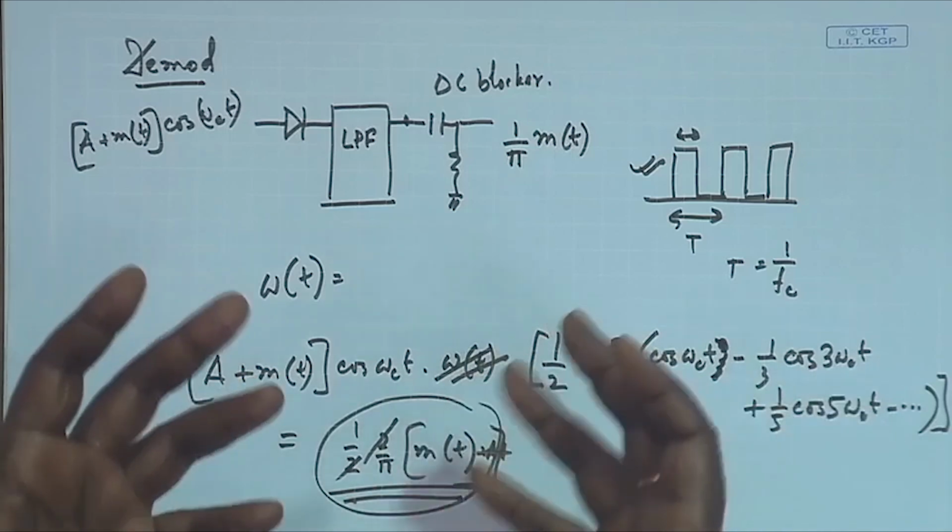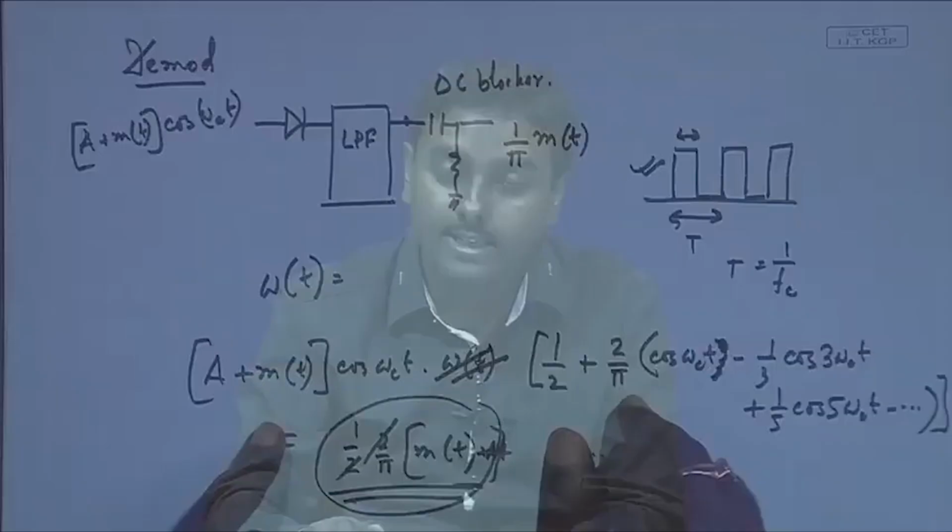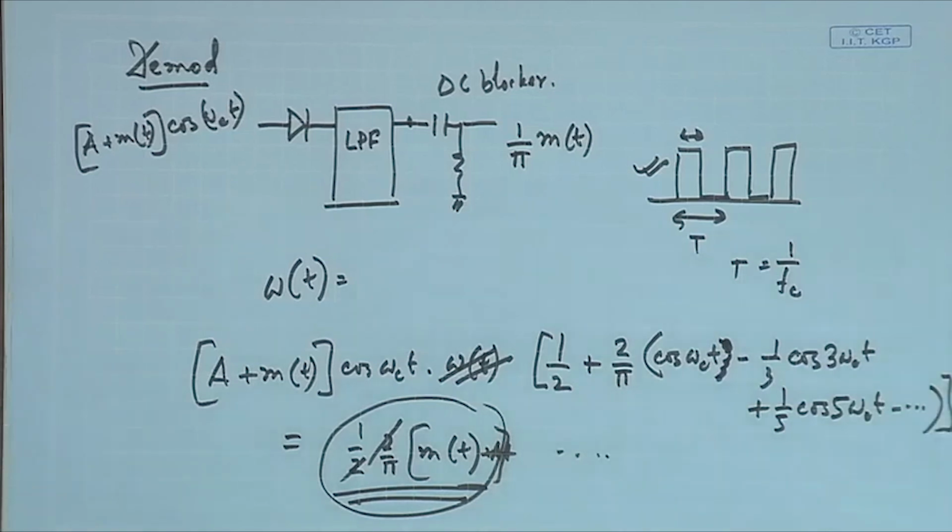Now, the diode is actually helping me to multiply it with Wt, which has a cos omega ct. Okay. So, basically my signal itself is carrying the carrier, which I have told earlier also. So, it has the carrier information, and with a diode I can actually do the multiplication and get everything out, I do not have to do any synchronization.